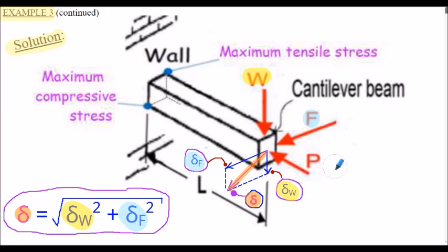Just note for reference, there would be a deflection due to the applied compressive force P at the end of the beam. As this is an actual compressive force, the beam would obviously shorten, but we're making the assumption that the deflection due to the applied axial force P is negligible compared to the deflections due to bending.